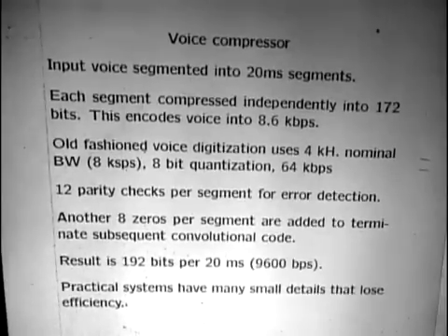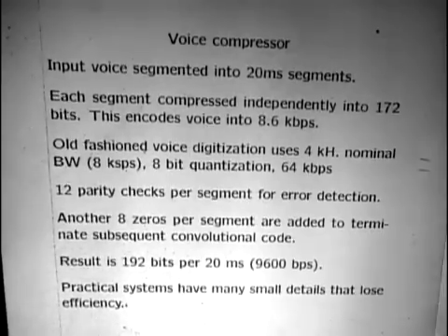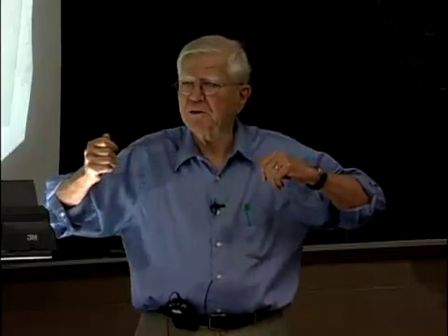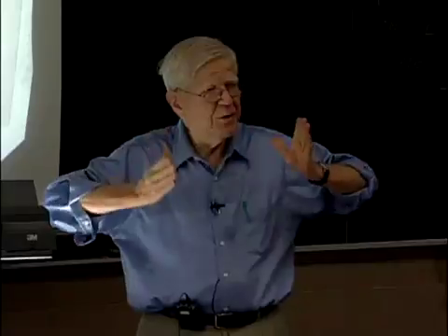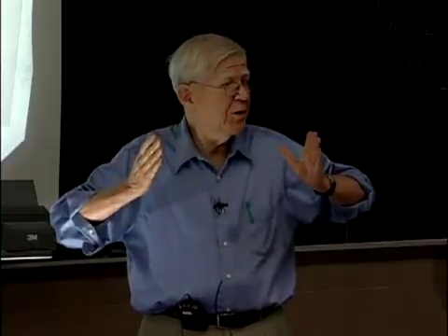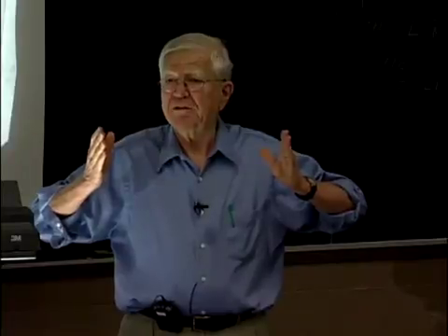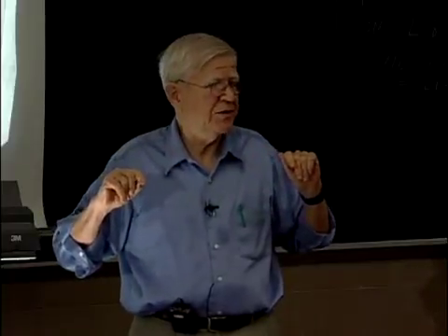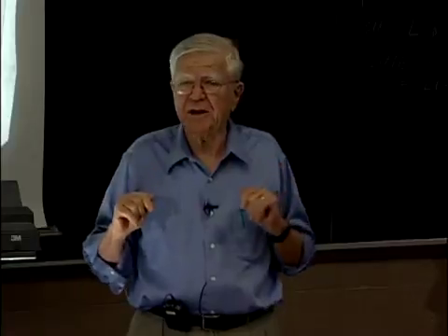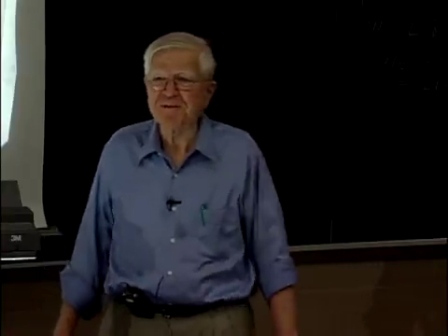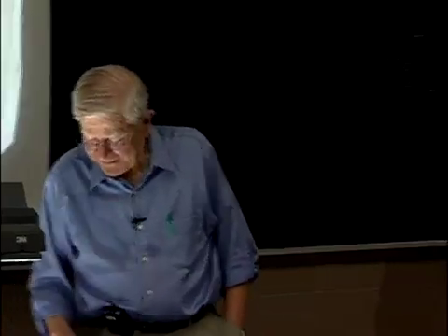The reason is if you take this 20 millisecond segment and you go through all of this enormous processing that we're going to go through, namely turning it into an encoded waveform, transmitting it, receiving it, detecting it, doing all the stuff we're going to do to it, if you get the 20 millisecond segment confused, and usually if you make errors, you make a lot of errors. So if at the receiver you wind up with the wrong thing, it is really going to sound awful. So they found that it's much better if you're not quite sure of what that segment is to just send silence for 20 milliseconds. And the silence is hardly detectable at all. It just sounds like good voice. For most of us, it really sounds wonderful to have a little more silence. Okay, then there's another thing.